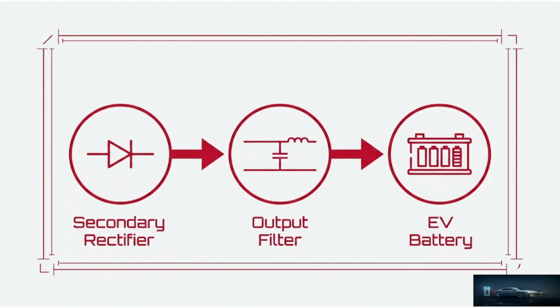Okay, so remember what happened in zone 2. We converted the DC into a high frequency switched waveform so it could pass through the transformer, if you can recall our last session. After the transformer, we need to rectify that secondary side waveform back into DC.